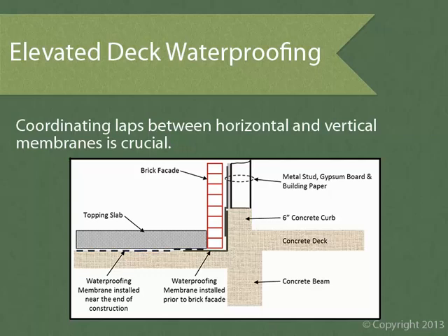First, it can be damaged from UV light. Most underslab membrane manufacturers prohibit their products from being exposed to direct sunlight for more than 30 days. Now this duration varies among manufacturers, but 30 days is pretty common. The reason is that the UV rays from the sun will dry and crack the membrane.